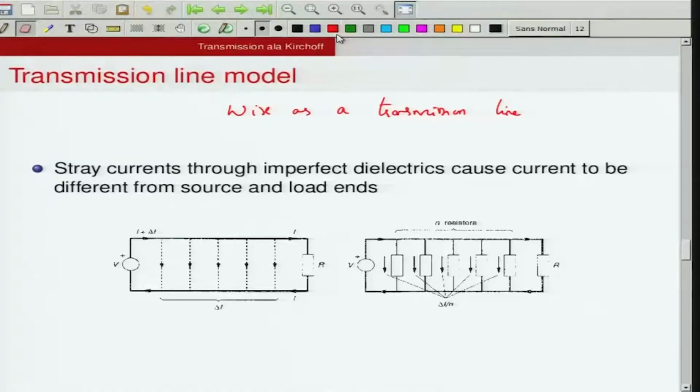There are situations, however, for example, you have an antenna, and you want to transmit something to this antenna. Then you need a cable running from the antenna terminals to the function generator, or the generator of your signal, which you are connecting. In this case, you want to treat this as a transmission line, because this is precisely the job of this wire. It is actually transmitting energy from generator to antenna.